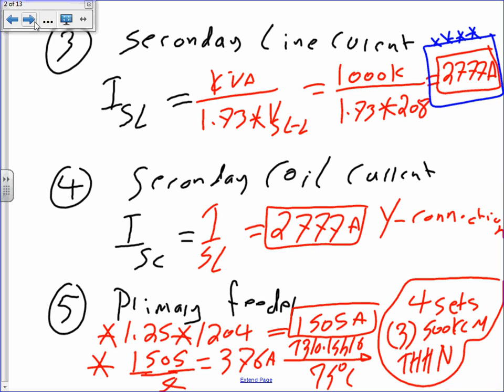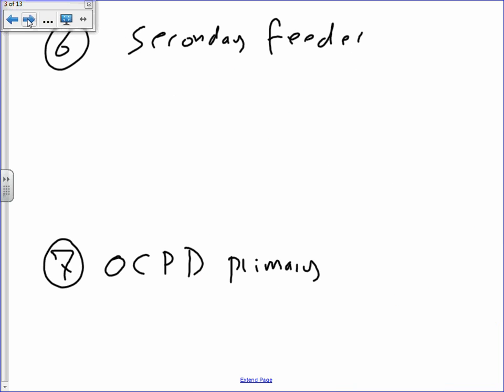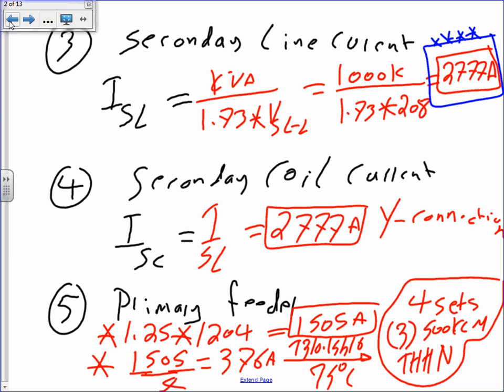Okay, any question, guys, about this? Shall we go to the secondary feeder? Now, I highlighted, guys, the cable that you use to size the conductors, right? This is always line, always line. Anybody knows why line? Because line is the feeder that's coming to the transformer, right?